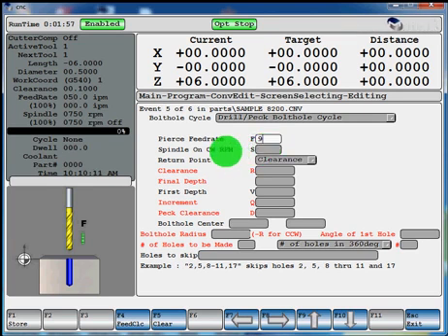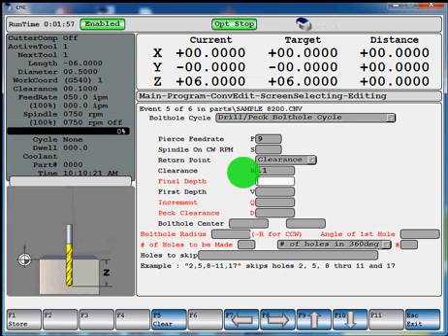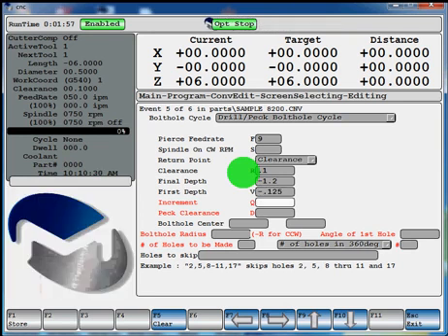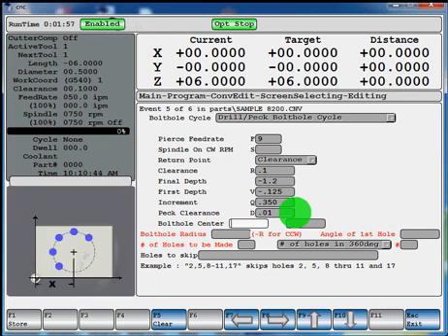So we're just going to hit enter to come all the way down to our clearance field. The clearance will be 0.1. The final depth will be -1.2. We're going to drill all the way through this plate. Your first Z depth and your cut increment and your peck clearance is just going to be the distance it's going to stop before it engages in the feed rate again after it pecks out of the hole. Your bolt hole center, we'll say the center of our block is X0, Y0.